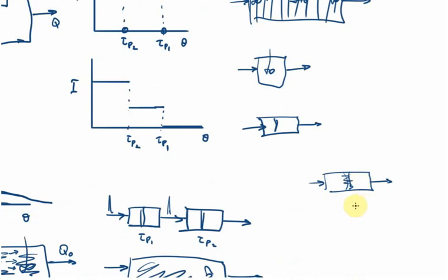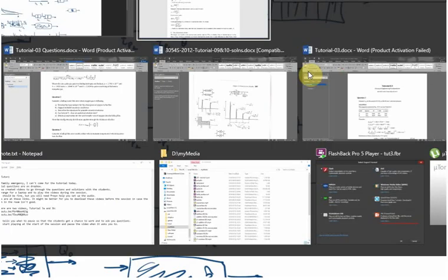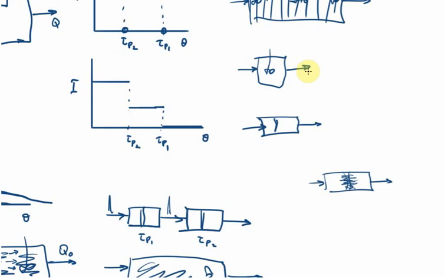What we want to try to do instead is introduce a concept of dispersion, and it's closely related to the concept of diffusion. So in diffusion, even as a plug of fluid is flowing along, the molecules in that plug of fluid are diffusing. So if you introduce diffusion or more generally dispersion on top of convection, is there some way we can get to CSTR-like behavior? So I'll let you think about that. And for now, we'll cover that topic in the next lecture.